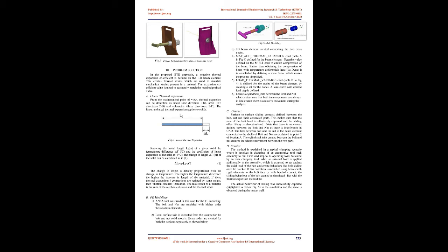The change in length is directly proportional with the change in temperature. The higher the temperature difference, the higher the increase in length of the material. If these thermal expansions/contractions are resisted by some means, then thermal stresses can arise. The total strain of a material is the sum of the mechanical strain and the thermal strain.